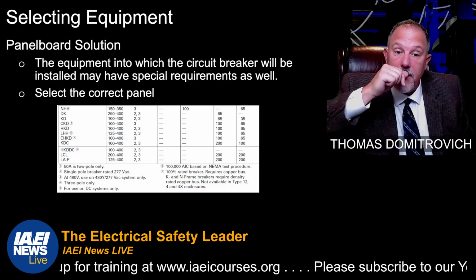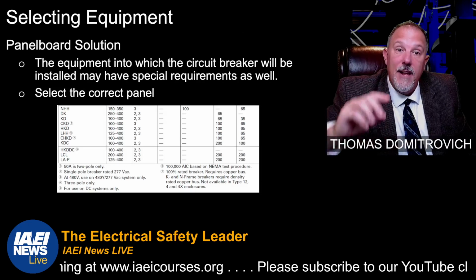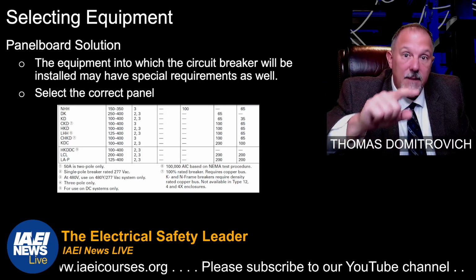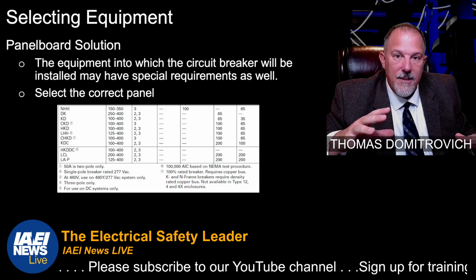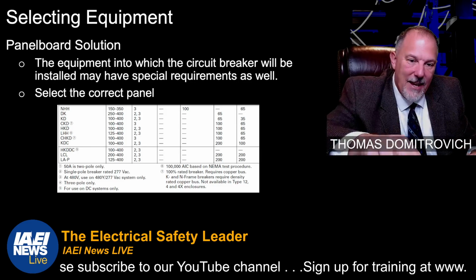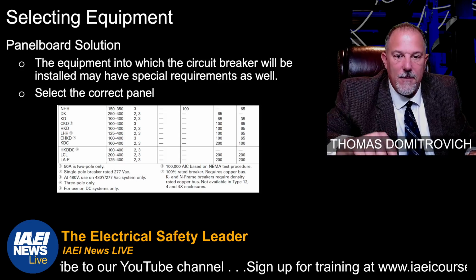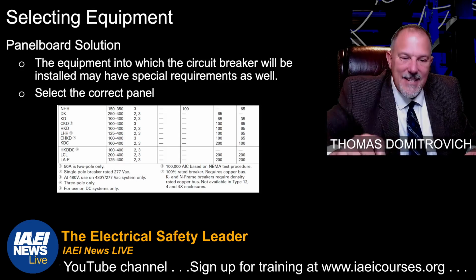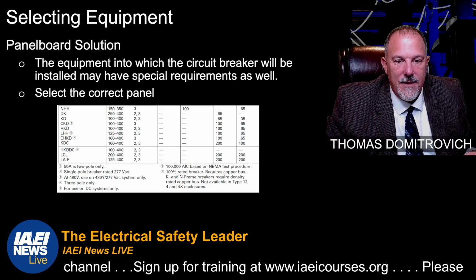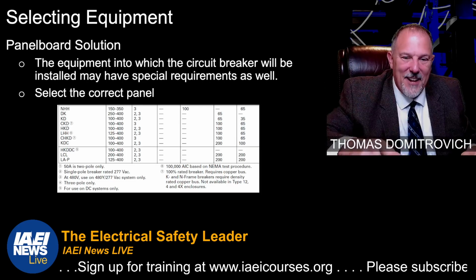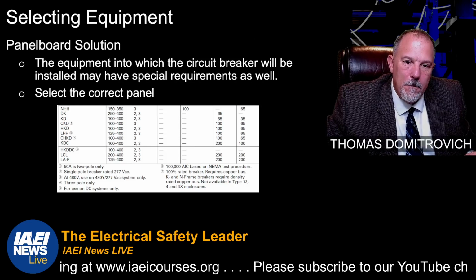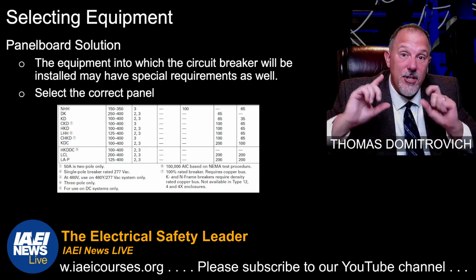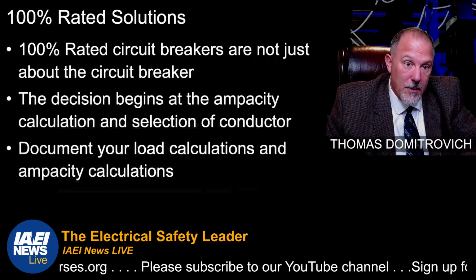So those two specific circuit breakers, if they're going to be placed in this catalog number of a manufacturer, if you buy a K or an N frame from that manufacturer, you're going to need density rated copper bus. And, oh, by the way, it's not available in a type 12, 4, and 4X. It's not as simple as just replacing a circuit breaker.